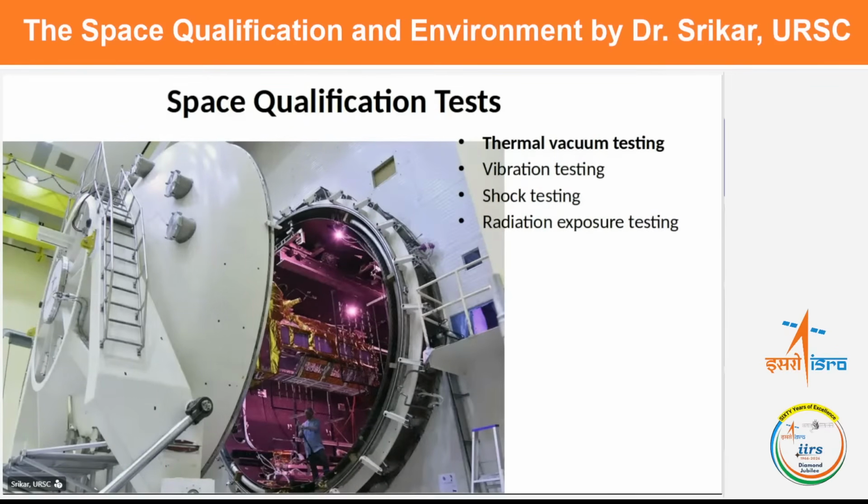Because of that, the system will undergo thermal fatigue. So what we ensure by this thermo vacuum testing is that all the systems are robust enough to withstand those temperature changes, and also the vacuum condition. So they're able to radiate out the heat whenever they need to, and still maintain structural integrity, and so on. It's a huge test that will go on for weeks for each satellite, and it's also done at subsystem level. It's essentially one of the main qualification tests for space.